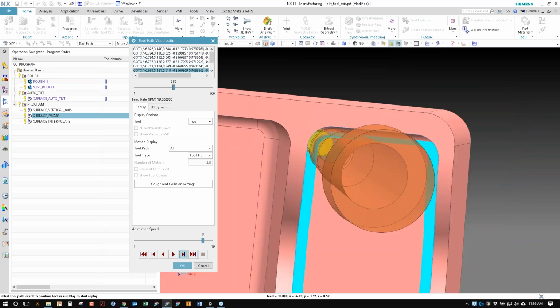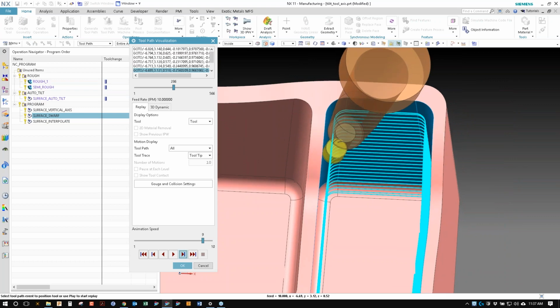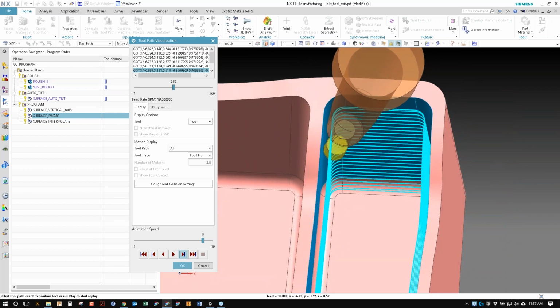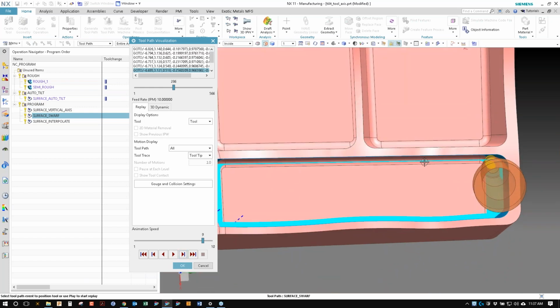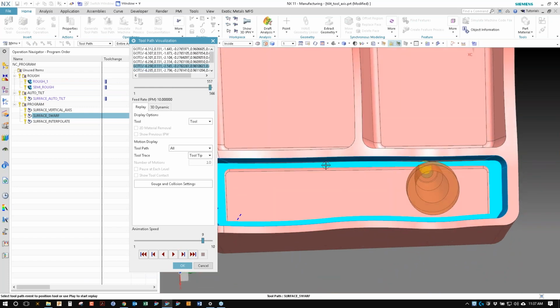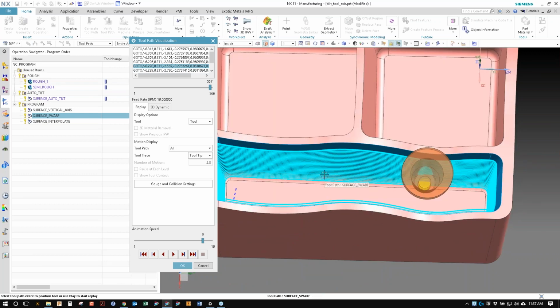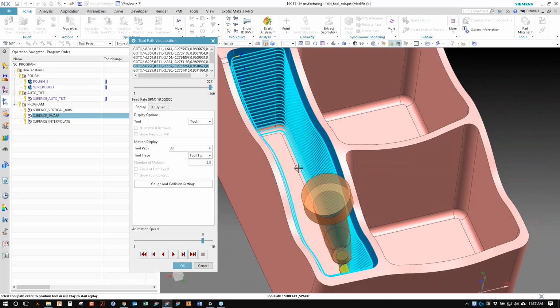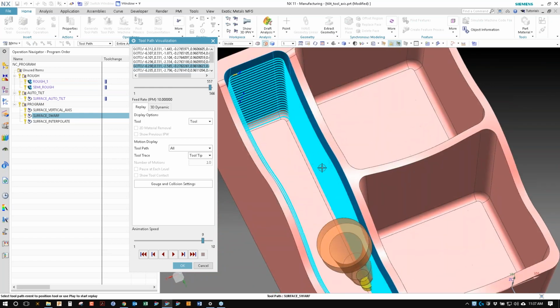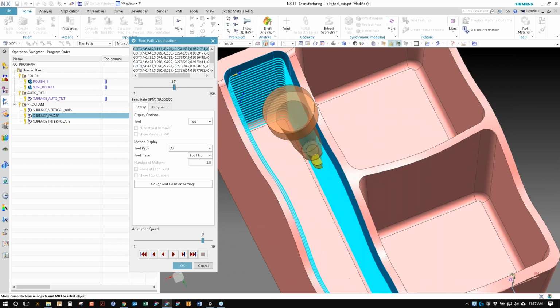From point and from line are other methods that would work, but you'd end up having a lot more swing than would be efficient on the machine. It would end up running a little slower because from line or from point would have tilt along sections where it wouldn't necessarily need tilt. Anytime you're using your rotaries or your other kinematics, the more often you're using all 5 axes, the slower it's going to run, and the less smooth it's going to run.